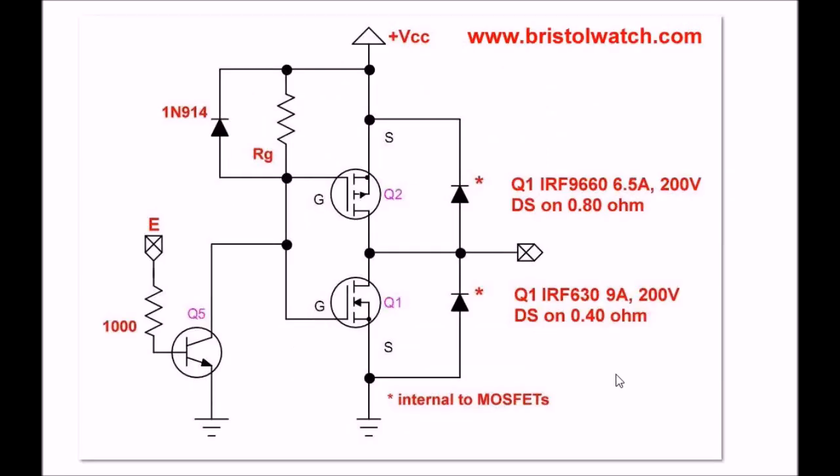What about a drive circuit? When you put MOSFETs in parallel, of course, the capacitance is going to add. You cannot change that. But you might be able to change R. Go back into your drive circuit. If you're wondering what this circuit is, it's half of one of my H-bridge circuits that I've had around for years. But it would be excellent for this application. Let's look at it this way. This goes to your MOSFETs, your gates that are all connected together.